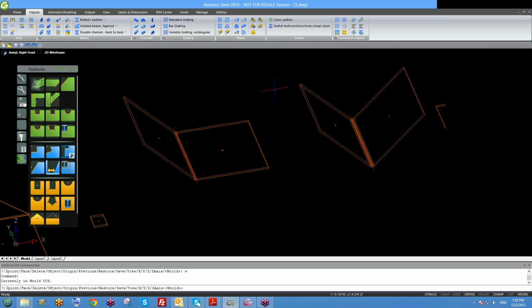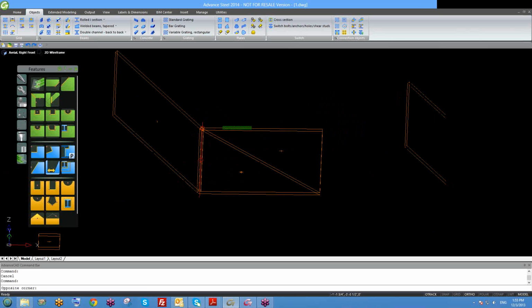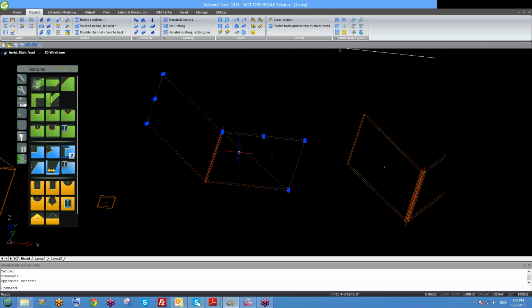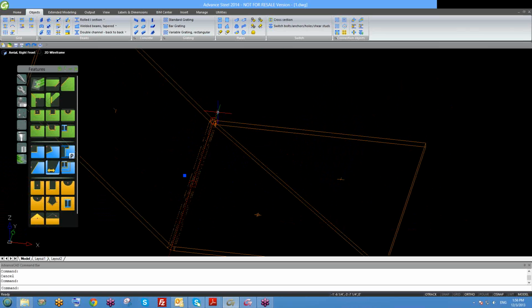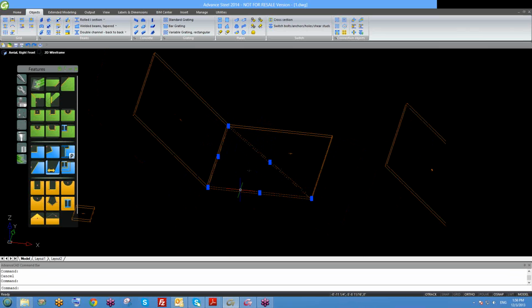All right. So I use the command split plates by 2 points. Select the command. Take a look at the command line asking for the plate. Pick the plate, then 2 points, 2 diagonal points maybe. And I've got 2 individual plates. But as I have just 2 plates connected to each other, it's like I have them all connected to each other. So if I delete them, you're going to see I've got 2 individual plates.